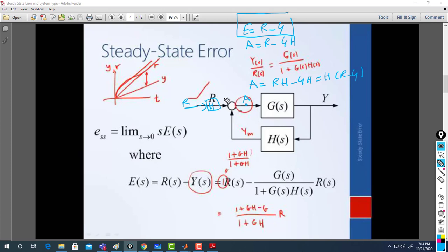So then you are comparing voltage to voltage. Then you get a value proportional to the error, which at the end is an error, but a different error. Let's say E prime, and this is E. Okay, I understood what you mean. But then we haven't obtained the real error. Yeah, the error is R minus Y. You just need to pay attention to the definition of error.